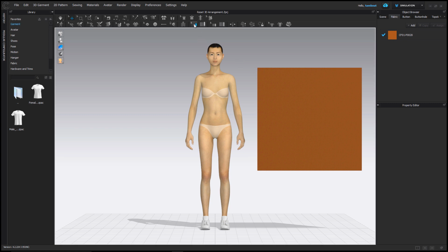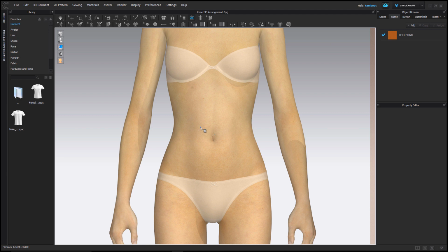Use the circumference avatar tape to create a circumference marking that you can measure. Hold Shift to activate guides to ensure your measurement is aligned. Left-click once to begin, then click once more to establish your circumference. You can adjust your angle from here. Click again to end the tape measure.